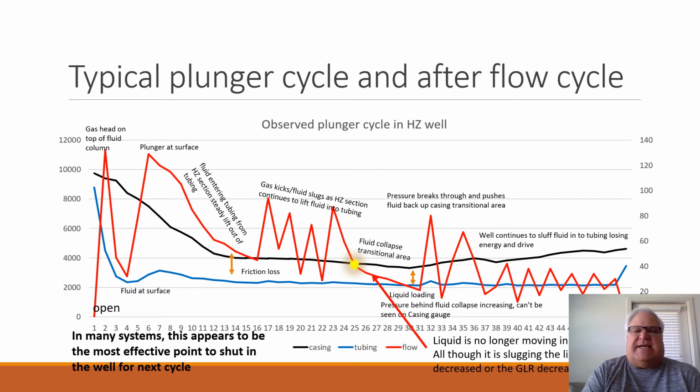So this idea allows these wells to move the water and other things that are separating in that horizontal section. It keeps it moving so you don't get a buildup of a much heavier fluid like water near the end of tubing that all of a sudden enters in one big slug and upsets the way the well's flowing, and they're dying at 2 million a day when they should be well above critical. So there's a real advantage with doing that.